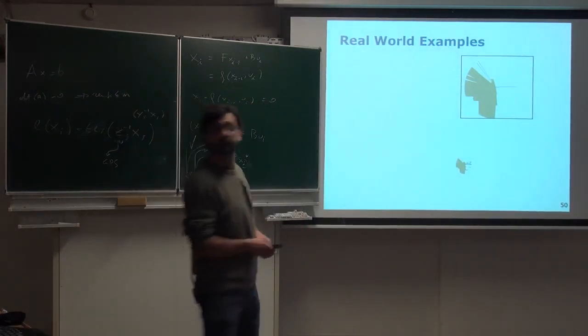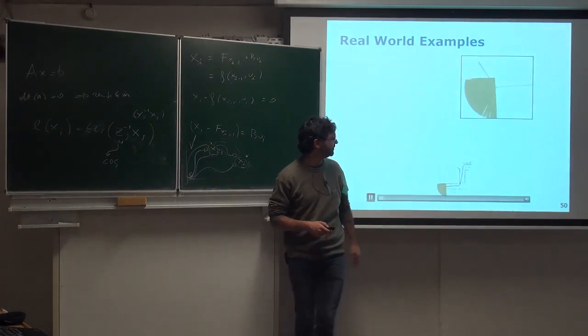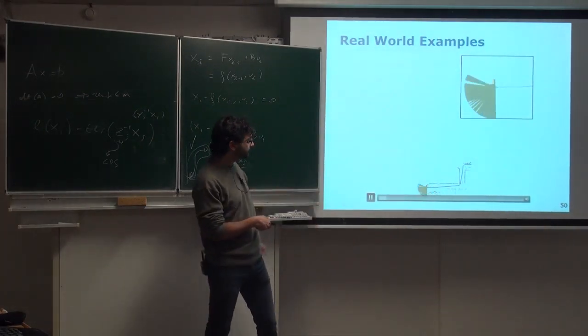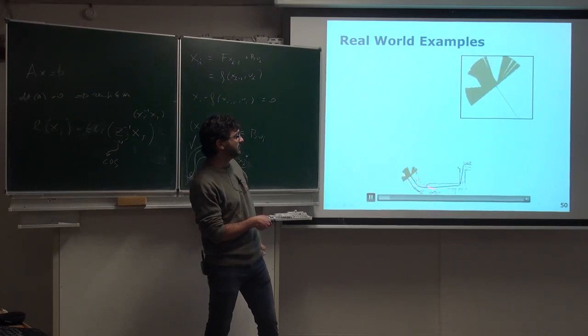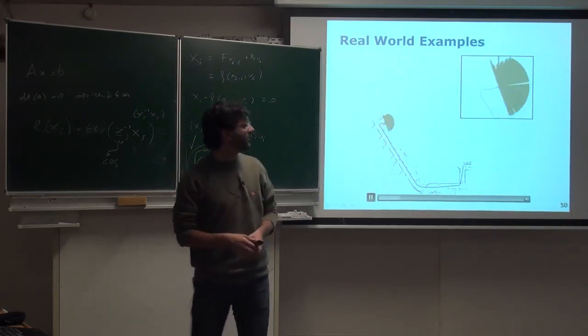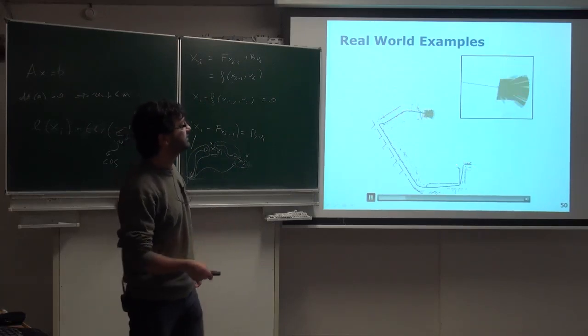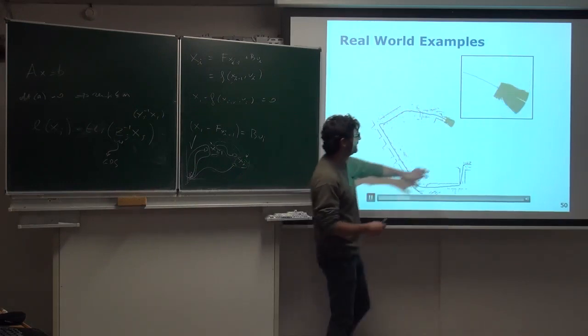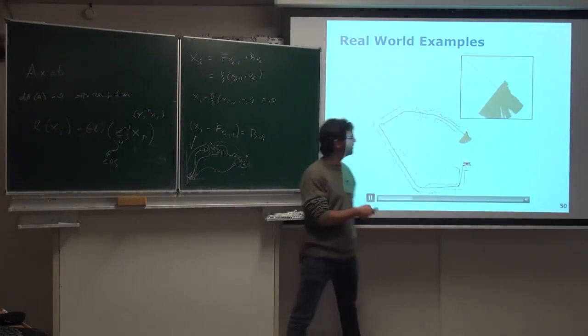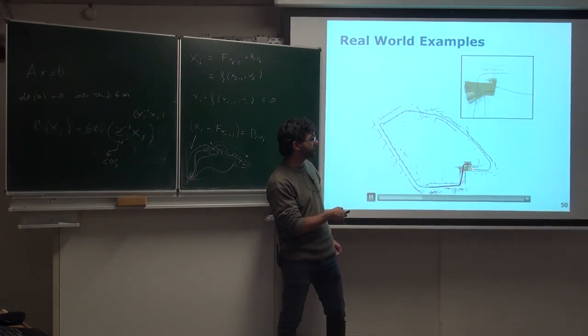There are a few interesting things to see. So you can see now the robot is moving around and is observing part of the environment. At the beginning, it's just collecting measurements from the odometry, so there will just be a chain of poses. The graph will just be one after the other. But soon it will come back to this part, and you can see here in red that the robot is reobserving part of the environment, so it's trying to get some of these poses together. It's trying to analyze if there are some connections.